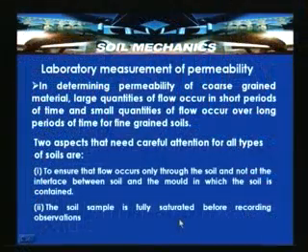So, two aspects need careful attention for all types of soils. The first aspect is to ensure that the flow occurs only through the soil, not at the interface between the soil and the mould in which the soil is contained during the permeability test. And the soil sample must be fully saturated before recording observations. So, this has to be ensured.